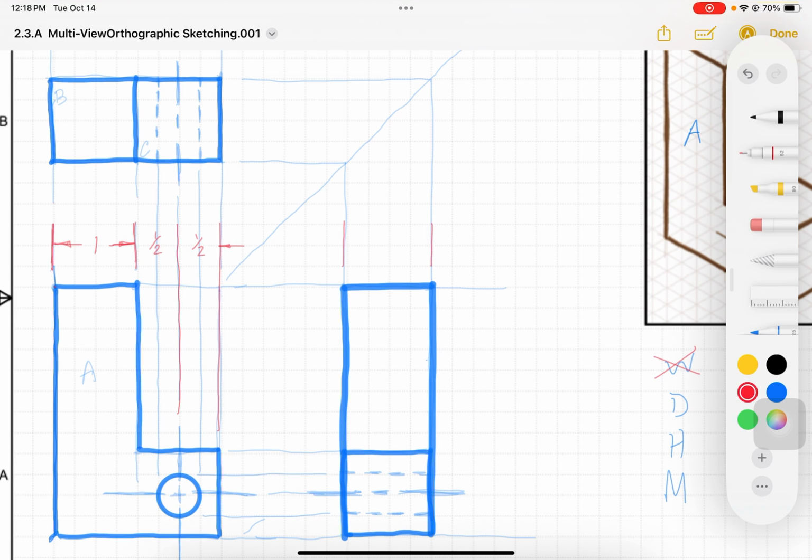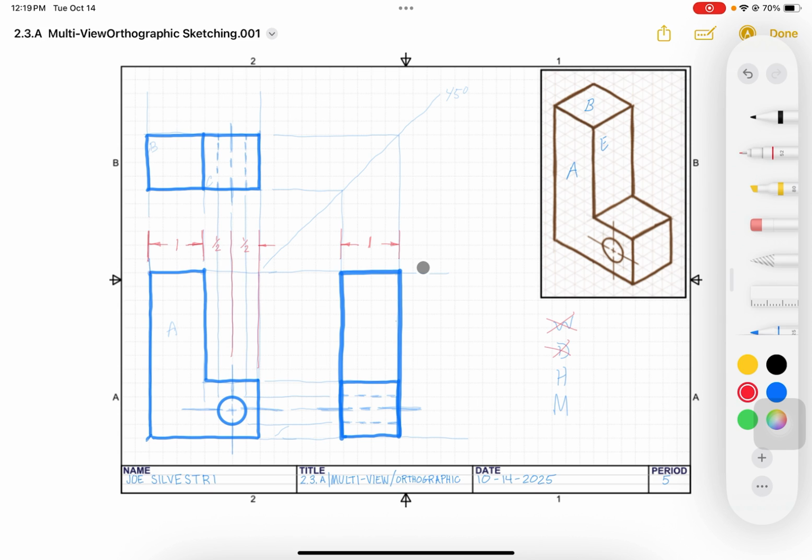This one's pretty easy. Again, make your arrows nice and little, fill them in, okay? So let's take a look at that 1-2-1 method again. I got a 1 block gap. The dimension line is 2 blocks away from the outer edge of the object, and then the extension line extends 1 block past. So that's a 1, 2, 1. So I'm just continuing that throughout the whole drawing. 1, 2, 1. All right, how deep is this? Let's see, it's 1/4, 2/4, 3/4, 4/4, or 1 inch. And that's it. I don't have any other depths. I can cross that off.